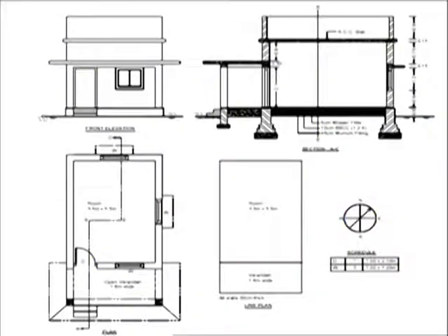Elevation is drawn first. After completing the plan, you draw the horizontal lines here, the line for the ground, then the horizontal line for the plinth, and you extend it from here to this end, because these horizontal lines will be useful for completing the elevation as well as the section. Similarly, the sill level, that also you transfer throughout, but you draw it with very light darkness, because afterwards some portion of those lines you will need to erase.